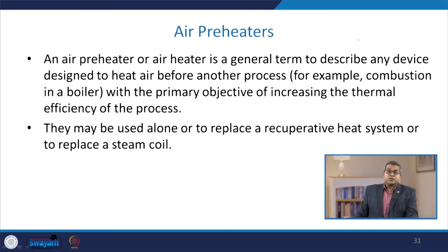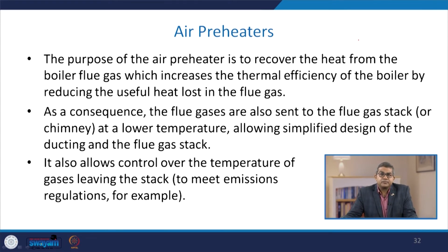Sometimes they may be used alone or replace a recuperative type of heat system, or replace a steam coil. The purpose of the air preheater is to recover the heat from the boiler flue gas, which increases the thermal efficiency of the boiler by reducing the useful heat lost in the flue gases.